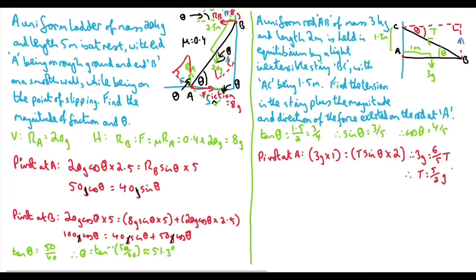So now then, why didn't I use the vertical equilibrium instead to try to solve it? Why did I go straight to the moments? Well, that's because I haven't drawn every single force on this diagram. There's also going to be a reaction force between the wall and the rod, as it's saying, the force exerted on the rod at A. What else is going to be exerting that force other than the wall itself? The problem is we don't know exactly how this force is going to be applying. We don't know if it's going to be coming straight to the right, or at an angle. It's probably going to be coming up this way here.